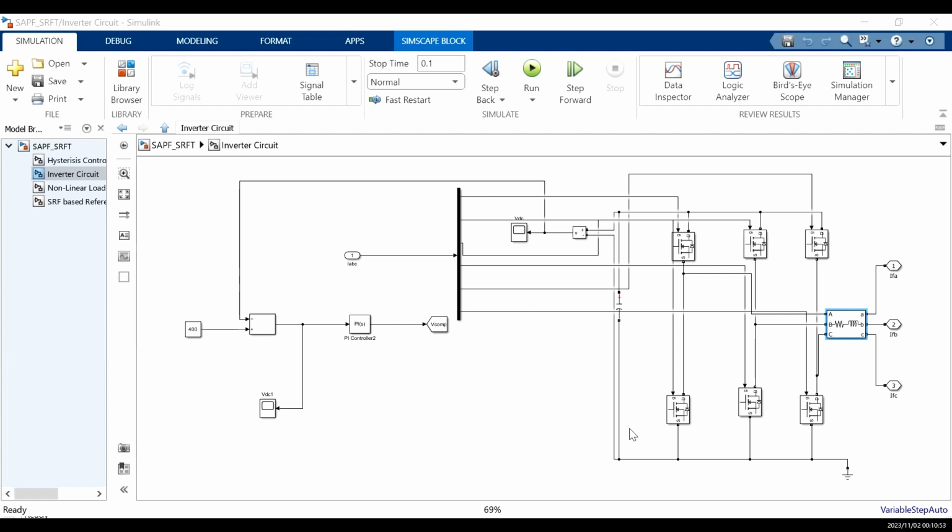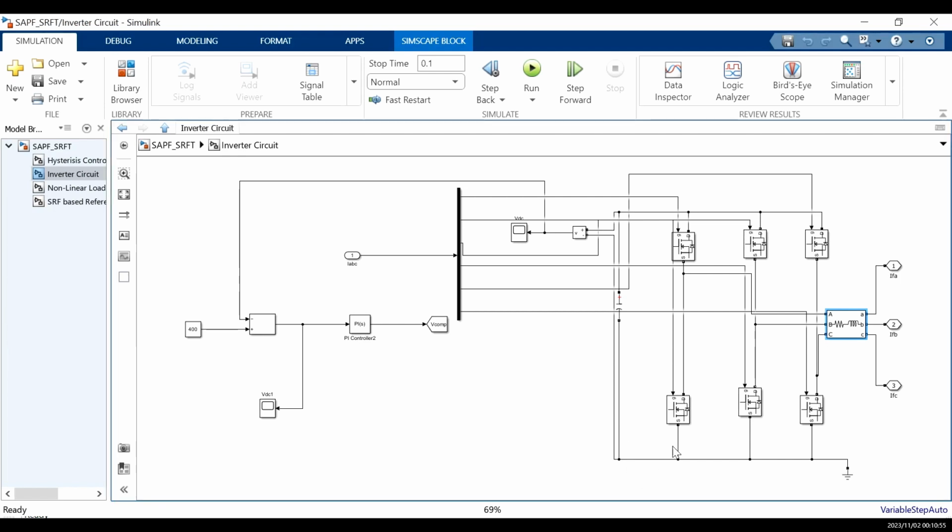It is a power electronic device that converts direct current (DC) power into three-phase alternating current (AC) power, enabling the precise control of voltage, frequency, and phase angle. The three-phase VSI operates based on pulse width modulation (PWM) techniques, allowing for efficient and flexible control of AC motors and other electrical loads. Operation principle.